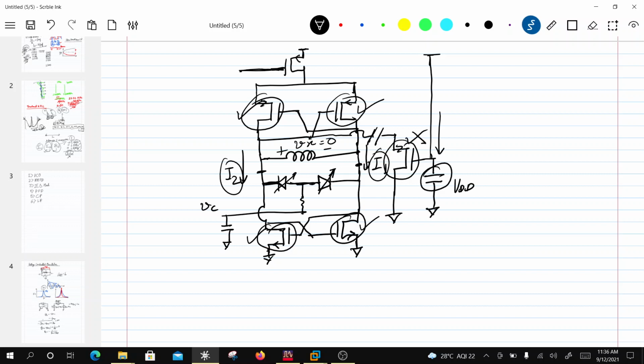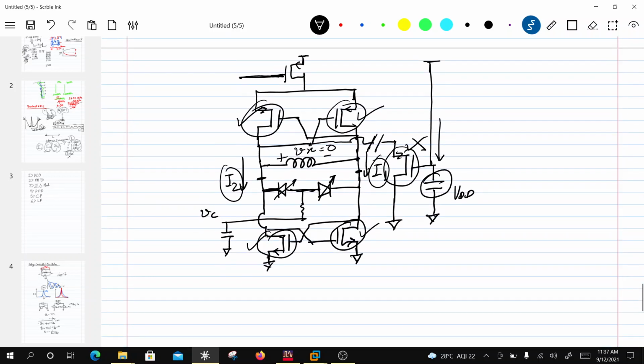Okay, now why is it important? Well, if you have these transistors balanced, the noise will go down, because then the noise is differential, and that differential noise would basically cancel out. So that is one reason why they should be matched. Another reason is that even harmonics would be canceling out. So this circuit is balanced.